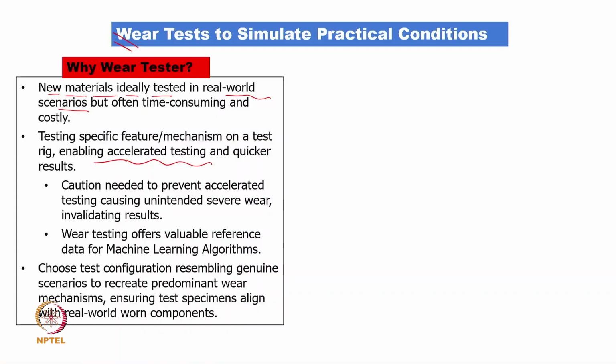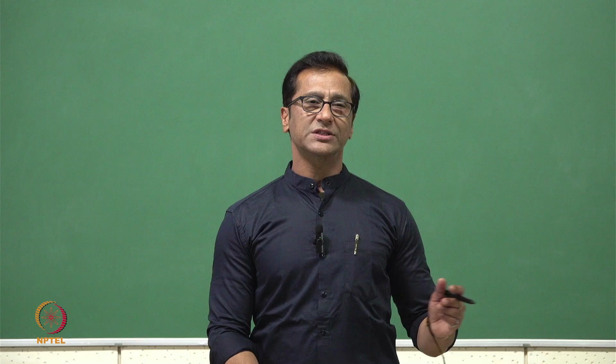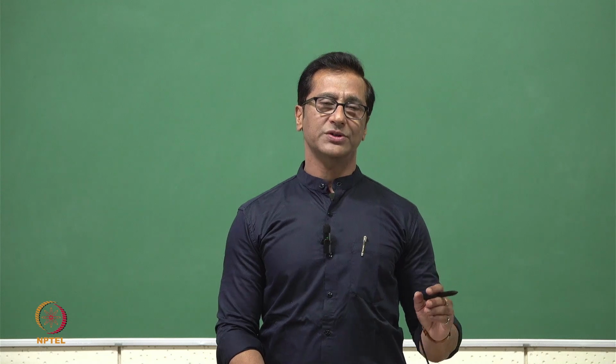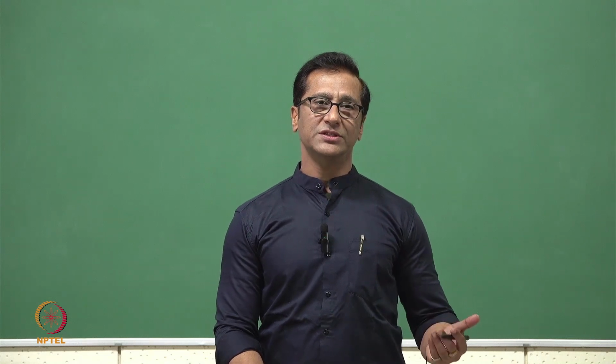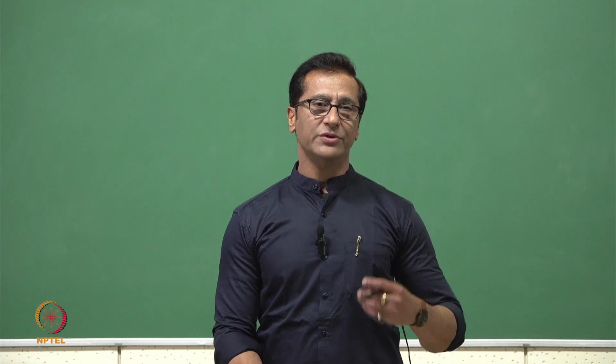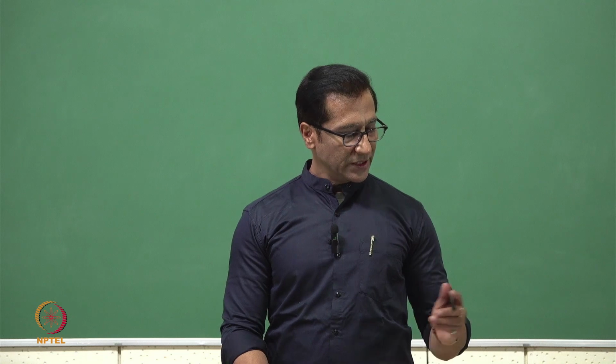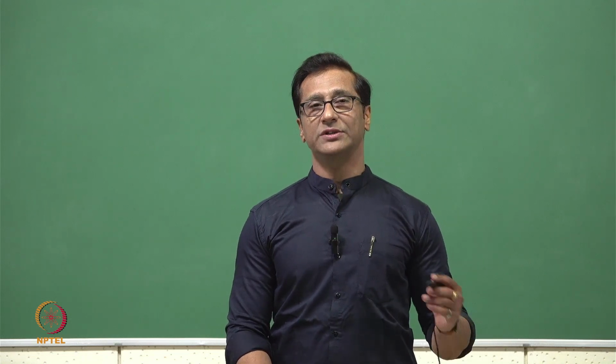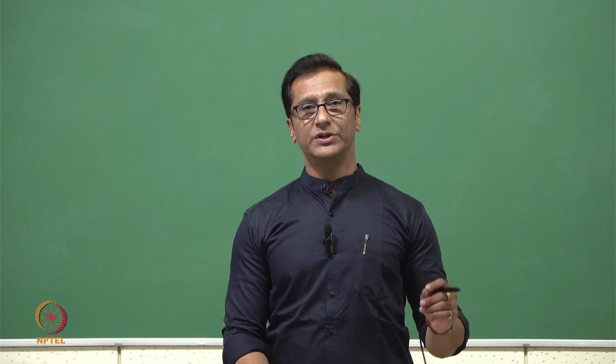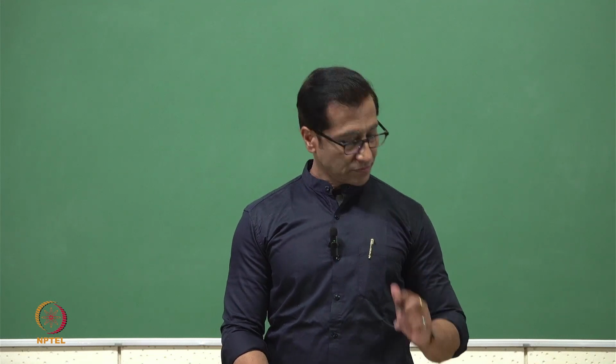However, whenever we go for an accelerated test, we need to make sure it does not change the wear domain. It should not jump from ultra mild wear to severe or very severe wear. We need to keep that in mind. If it remains in the same domain, there is no problem as such. But if the wear domain completely changes, then it is not giving a similar scenario; it is changing the mechanism. That should be avoided. That's why, when we talk about wear testing, we need to think carefully about whether whatever we are doing is really correct or not.